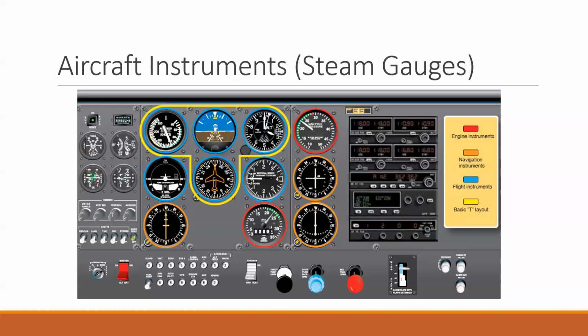You also have some radio navigation instruments below that manifold pressure gauge. The two below that are radio navigation, so you can shoot an ILS, or you can get a direction to a VOR off of those instruments. And then to the left of those instruments, below the vertical speed indicator, you have this RPM indicator, which is just indicating the rotations per minute of the propeller.